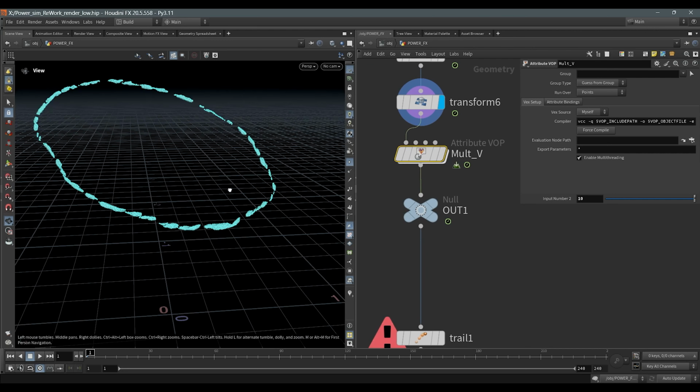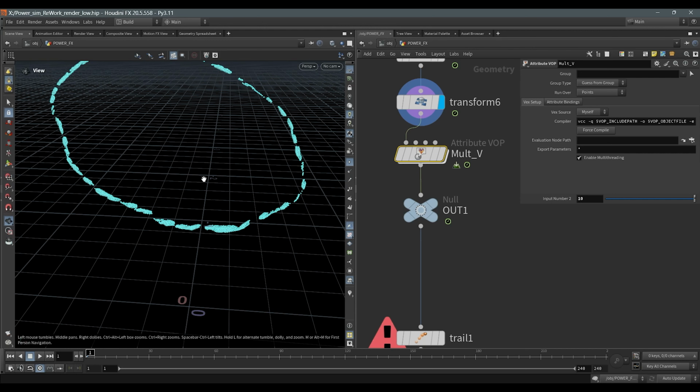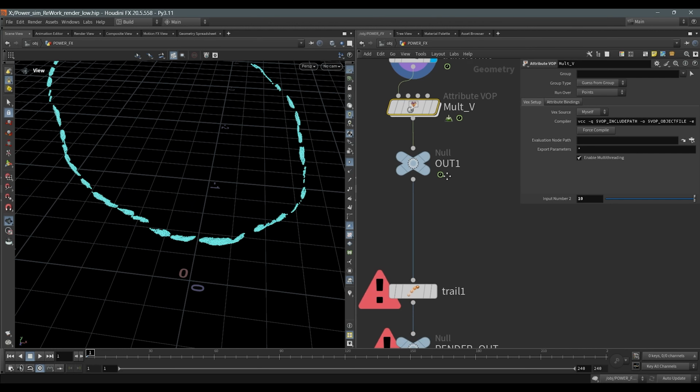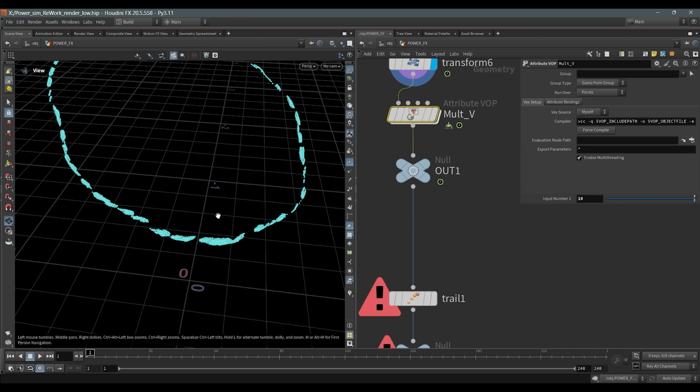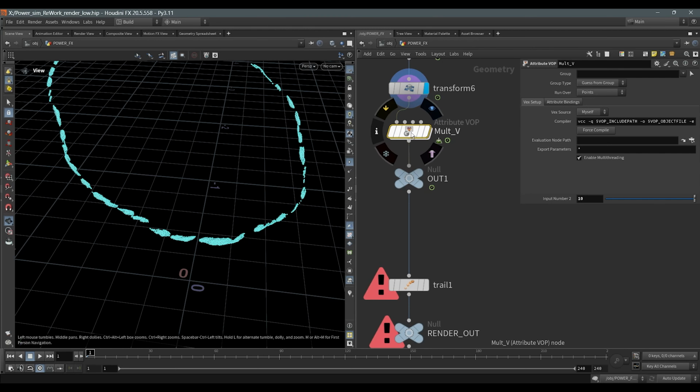Okay. So that motion blur is essential because if you don't motion blur your simulation, you will notice the individual points floating, and your simulation is stuttering. It's not a smooth simulation. So I need a motion blur, and that's why I multiply that velocity.